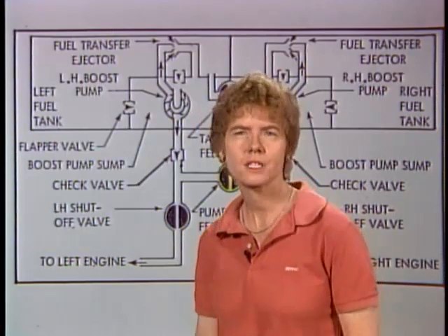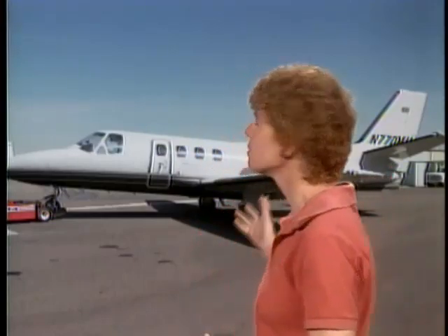Let's talk about fixing fuel tanks. Sometimes you need to repair a fuel tank. Now, if you're going to have to repair a fuel tank, you need to empty the fuel out of it first. And you want to avoid conducting any defueling and tank purging operations in any enclosed space. Do not do it in an air-conditioned building or any enclosed space. You want to be out in the open air in a well-ventilated area.